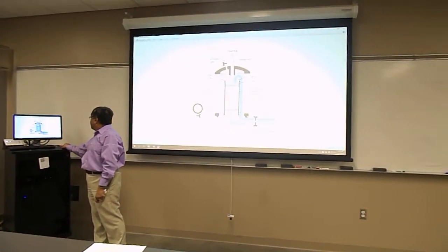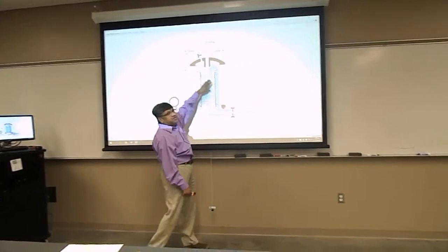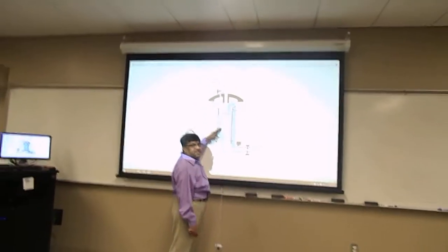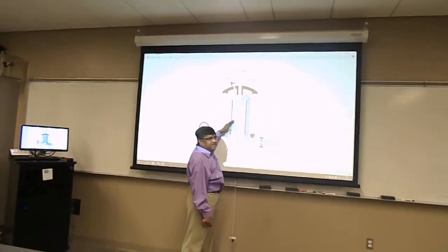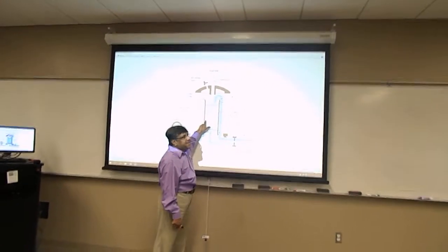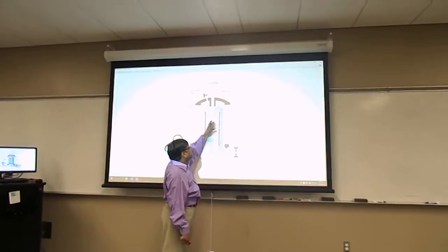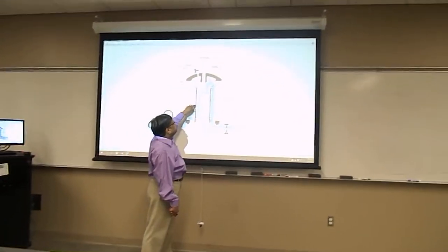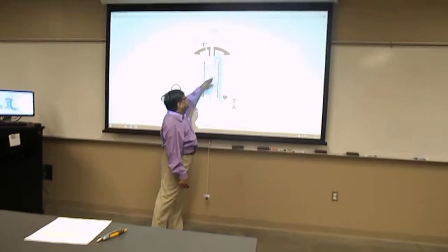angle. Most of the times the failure is internal. You don't even see the failure plane clearly. Even if you see the failure plane clearly, you won't be able to measure the angle because it's not possible. It could be even zigzag.